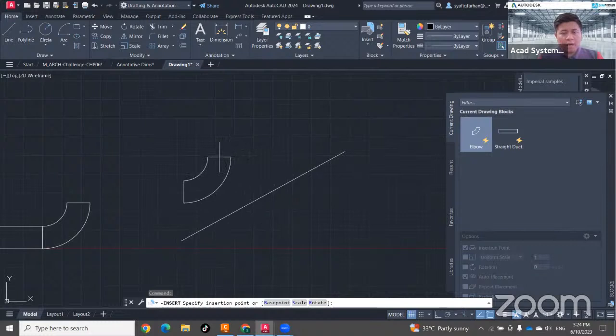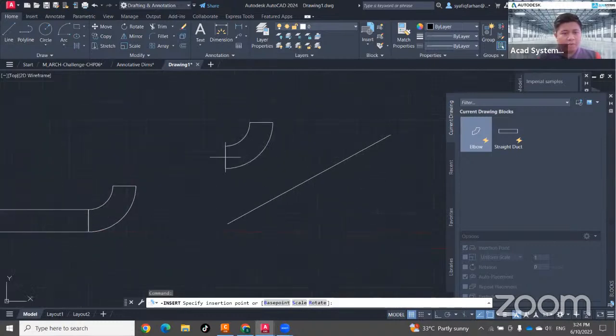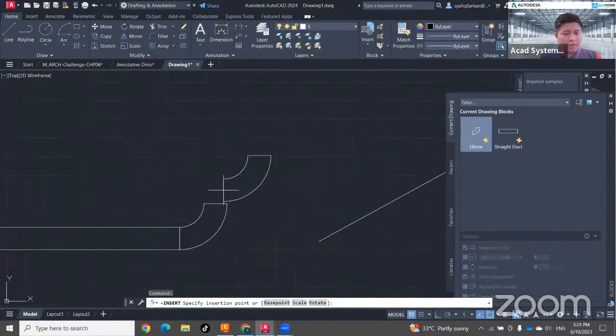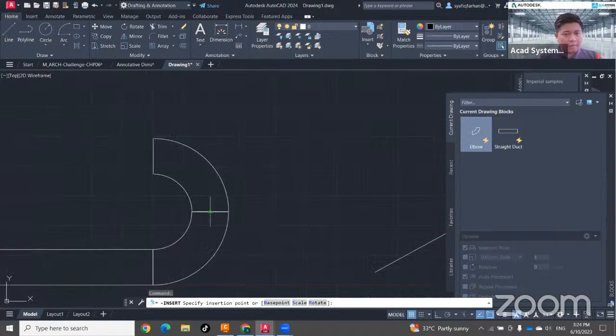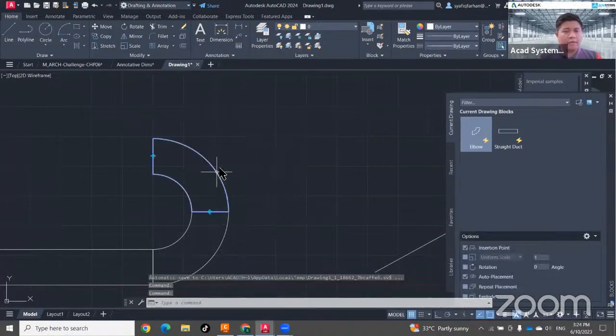Now when I mouse over this line, my object automatically rotates to follow the alignment line. So instead of inserting and rotating, better to make it an alignment. Same goes here. Instead of rotating later, I make it an alignment. Just insert first, later we can flip it.